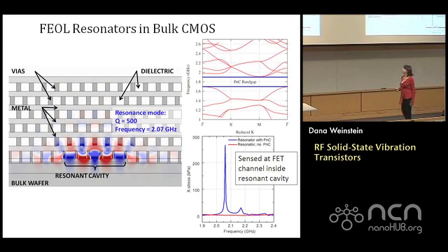So that's extremely painful. What I need to do is find modes that can be confined in the top of the silicon. And all I really have to work with is maybe shallow trench isolation and vias and routing. So we can actually use the vias around and above the structure, above the transistors, in order to form not one-dimensional acoustic Bragg reflectors, but 2D and 3D phononic crystals, which have particular band gaps based on their spacing.